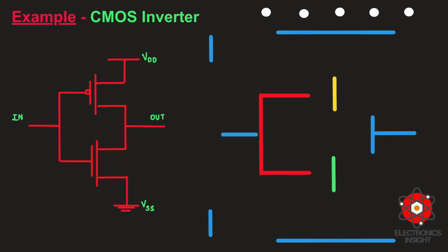And the interconnection where we need to join both these gates of NMOS and PMOS, right? That is also done with the polysilicon layer, because we are just extending the polysilicon layer so that both the gates are getting connected. And we need to take the input line, where I have also clearly mentioned that both the input and output lines are represented again using metallic layers, where metallic layers are represented using blue color.